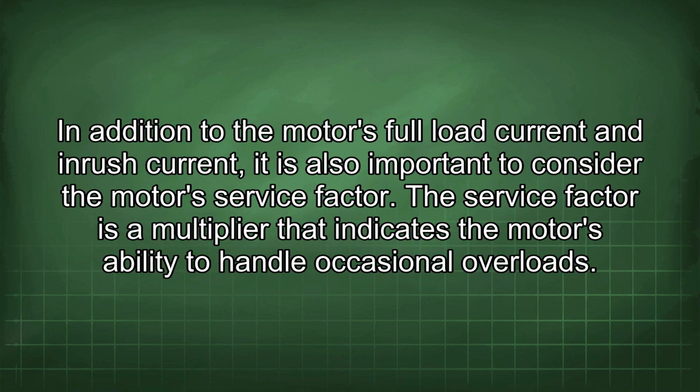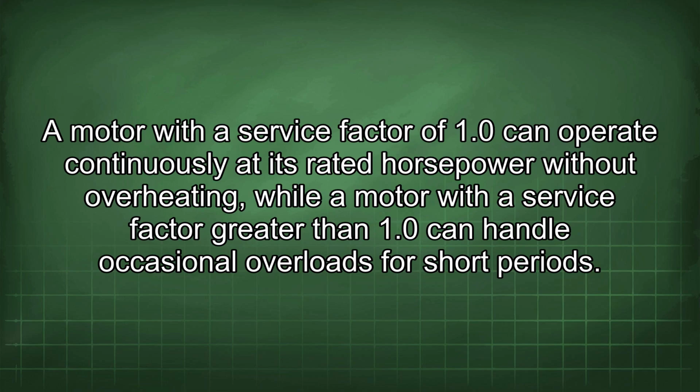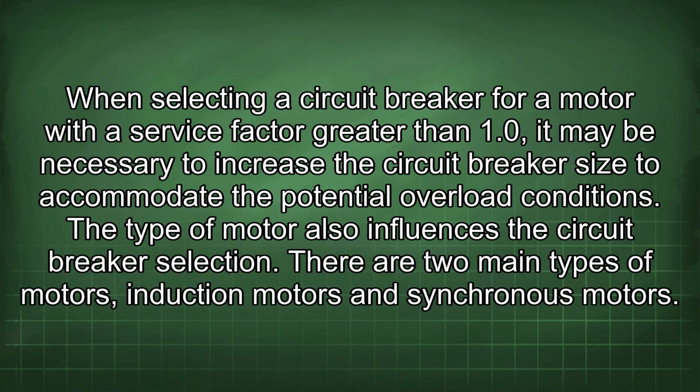In addition to the motor's full load current and inrush current, it is also important to consider the motor's service factor. The service factor is a multiplier that indicates the motor's ability to handle occasional overloads. A motor with a service factor of 1.0 can operate continuously at its rated horsepower without overheating, while a motor with a service factor greater than 1.0 can handle occasional overloads for short periods. When selecting a circuit breaker for a motor with a service factor greater than 1.0, it may be necessary to increase the circuit breaker size to accommodate the potential overload conditions.